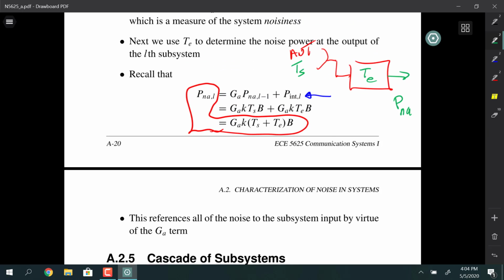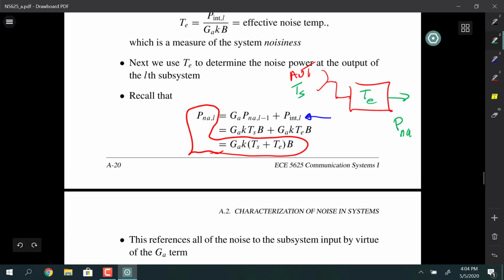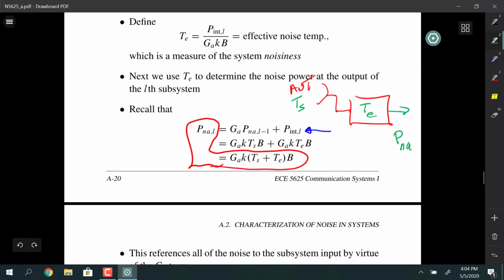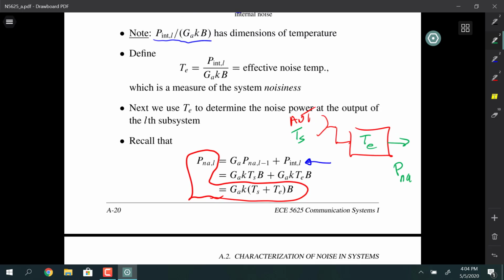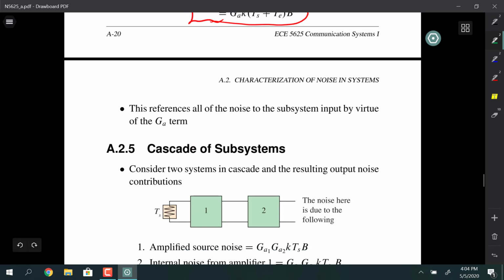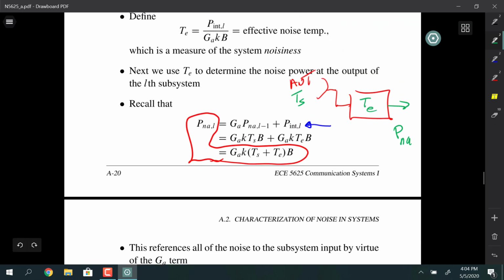I don't know if that's interesting or not, but I've certainly had people in this class before that have talked about how noise temperature of the source has been a factor. They've been out in the Middle East or something where they were trying to point to a satellite, and the alignment of the satellite and the sun were coincident just for a short period of time, and they couldn't receive their satellite signal because the temperature of the source was just way too hot because the antenna was pointing right at the sun, and the satellite was right in that line of sight. It was not on the other side of the sun, obviously, but in front of the sun, and it was just too noisy when they had the antenna pointed straight towards the sun.